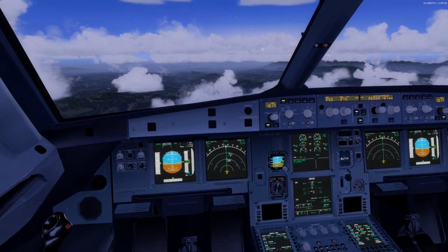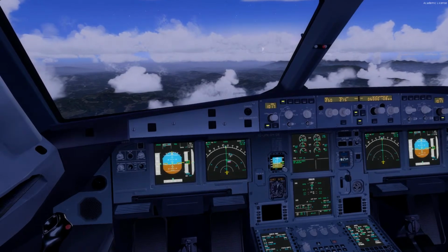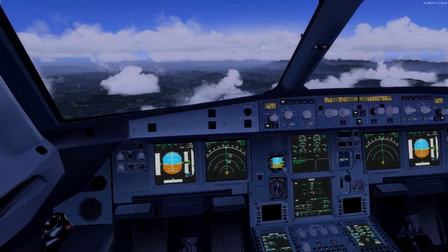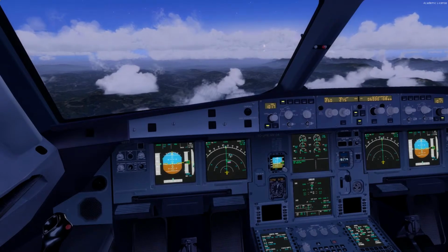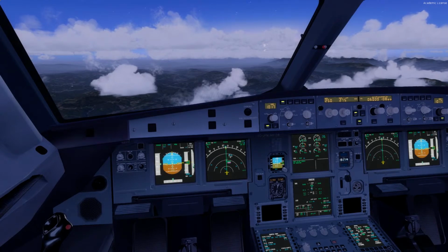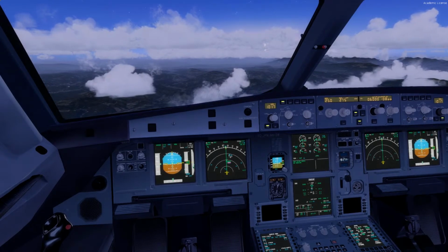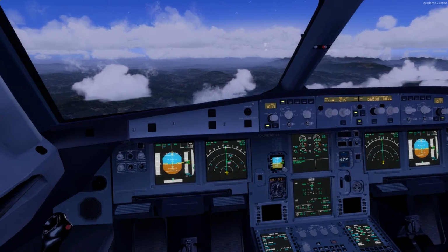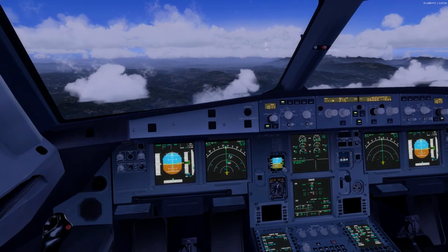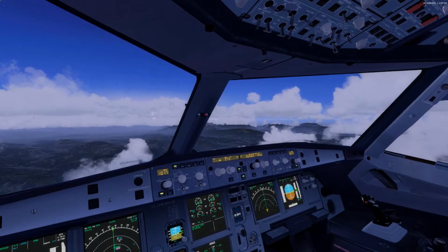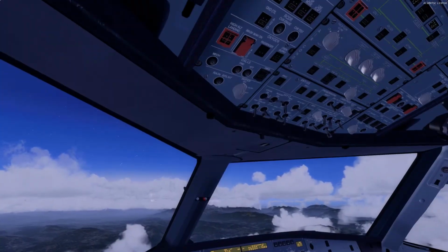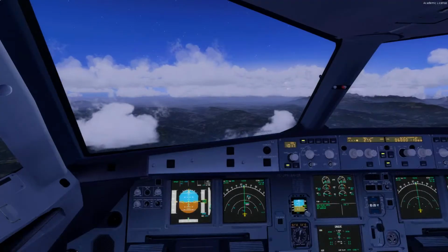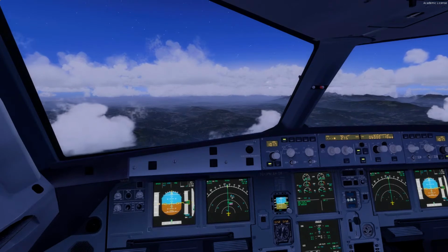And then we'll be cleared probably to 4,000 feet, as this is the altitude to intercept the localizer and the glide slope for runway 30 at Ljubljana. And as we are below the flight level, the 10,000 feet, we can turn on the landing lights, and the seatbelt signs will be also on. That's it for now, and still 15 miles to go.